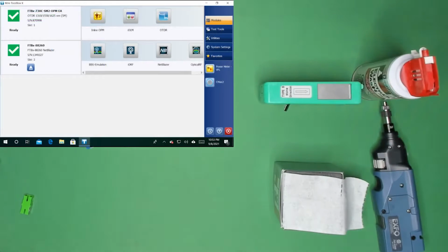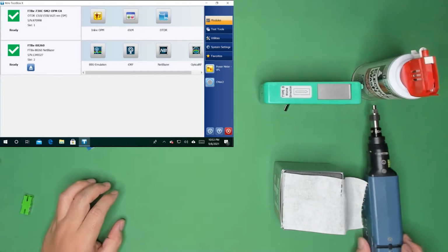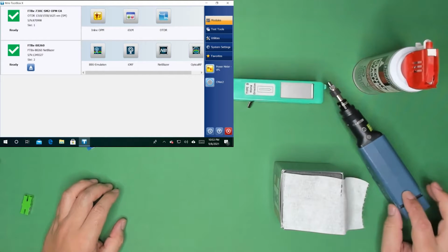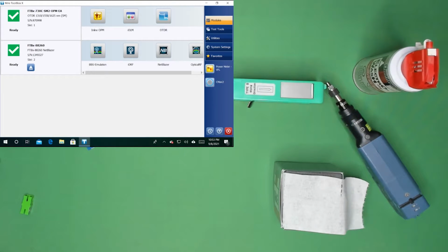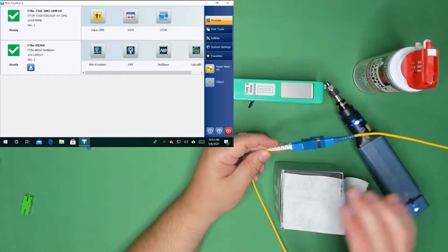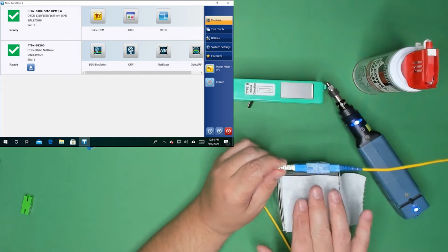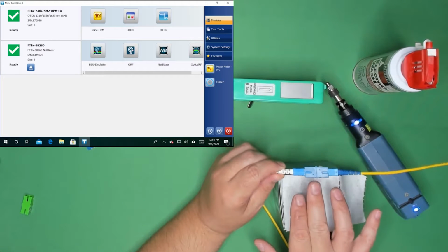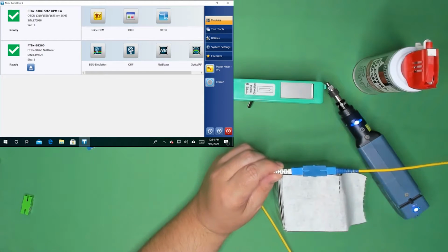So one thing I wanted to show is what cleaning a connector looks like with an OTDR trace. So I'm going to go ahead and fire up my FIP 435 here, so my inspection probe. I'm going to go ahead and fire that up real quick and let it launch. And then at the same time, I'm going to bring this fiber into the scene here. So essentially, this is a Sam Charlie SC UPC connector. I think it's about 150 meters out from my launch. We'll find out here in a second, right?